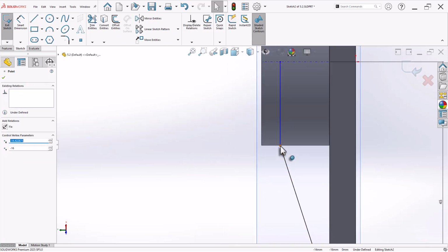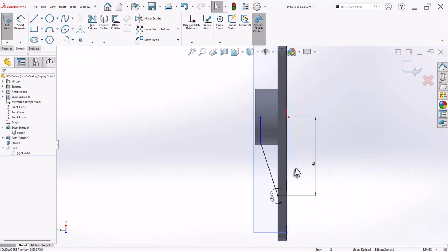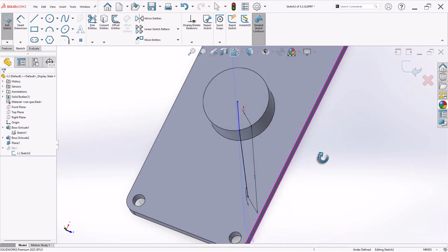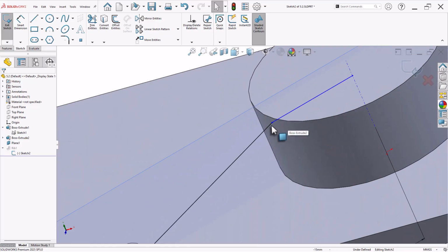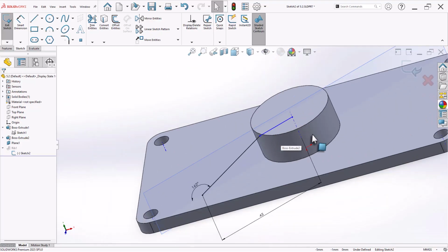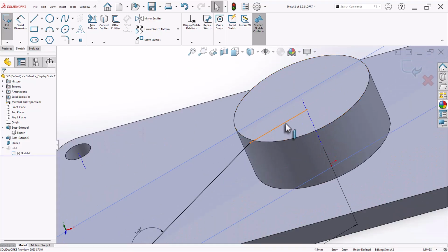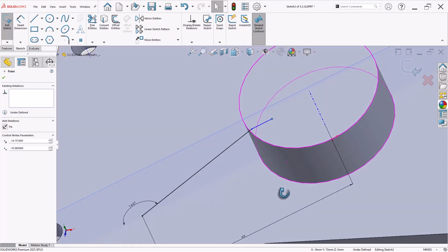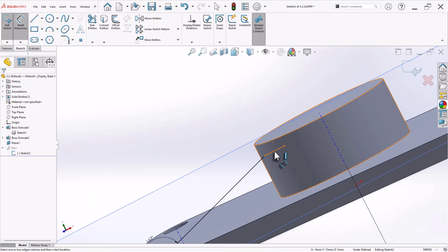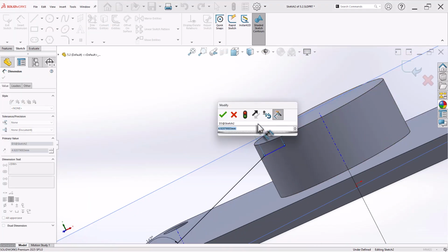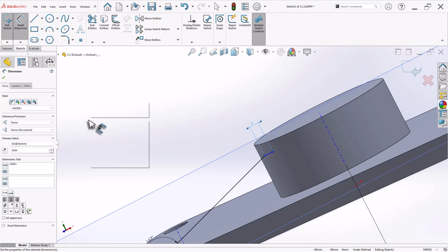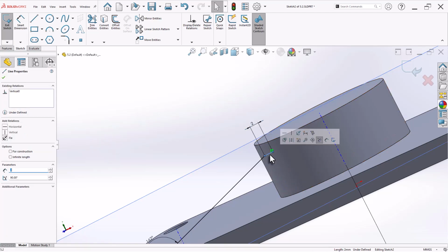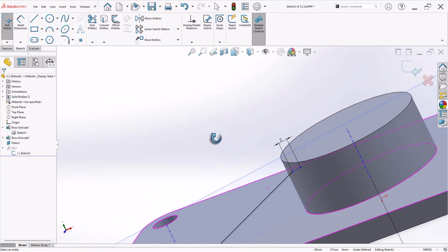Instead, let's click it and extend this material up to like this, because it is controlled by the angle. So it doesn't matter how much you go inside. Clear? Now let's say instead, now let's give some dimensions over here, let's say 2 millimeter. And also let's convert into construction geometry.